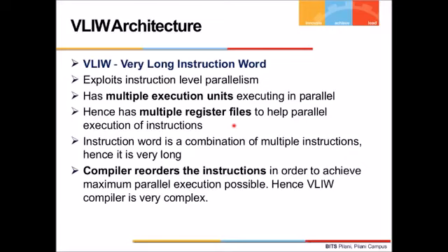You remember I was talking about instruction decoding. When an instruction is fetched, it comes as an instruction word. Okay, so that instruction word has to be decoded by the instruction decoder. So in the case of VLIW, what happens? A pack of instructions comes as one long instruction. Okay, and these instructions are separated out at the execution unit.